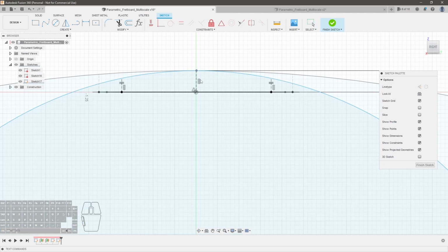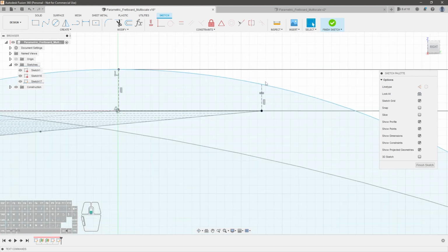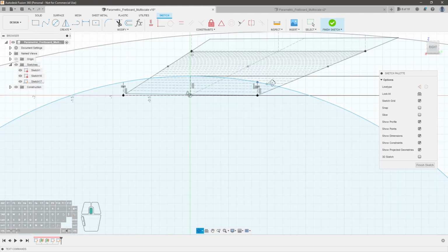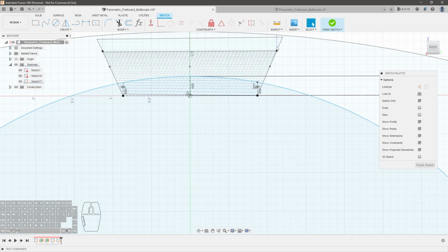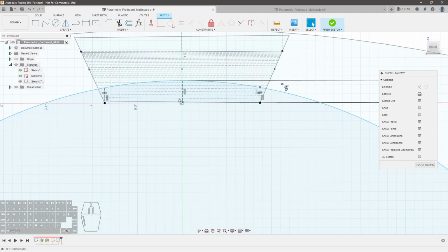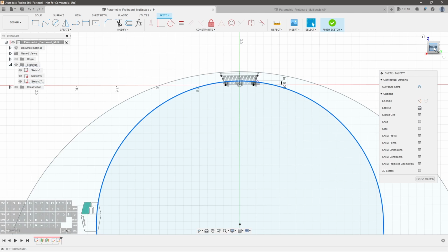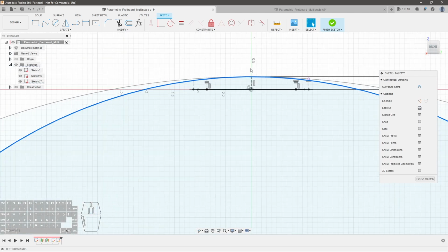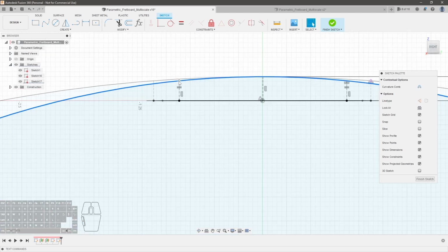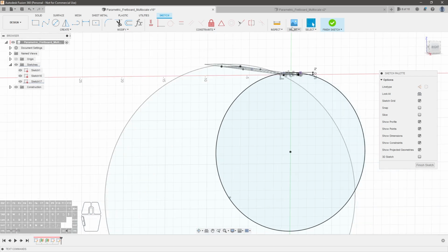So in this case, what we have is the same thickness, but all we have to do is make this horizontal to that point again. So let's project in that point again, because I lost it. Make those two horizontal to each other. And you'll notice this circle is fully defined. Can't define the radius because there's only one radius that touches through all three of those points. And so let's go ahead and measure that and see what that looks like.